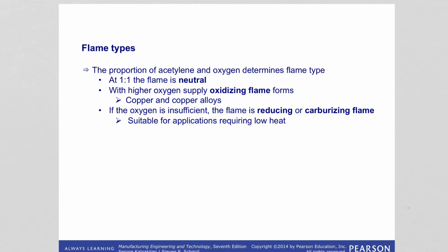If the ratio is 1:1, the flame is neutral. Most welding is done with a neutral flame because it will have the least chemical effect on the heated metal.